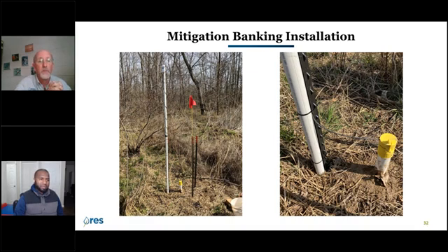Yeah, absolutely. And thanks for pointing out the height of that receiver, the communication piece. When we talk about that 1,000 to 1,500 feet, that assumes that the transceiver is at a height of about 1.8 meters or 6 feet. I like to say height is your friend. The higher you have it, and the further away you are from the ground, the better, because the ground does absorb quite a bit of that radio communication. The higher it is, the longer range you will get as well. So that does help.